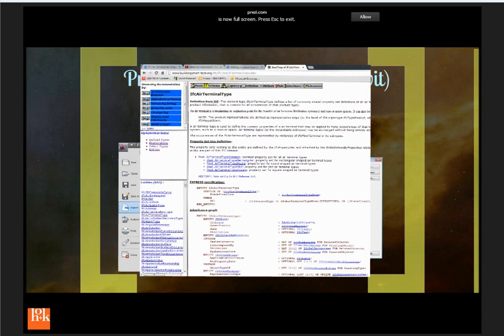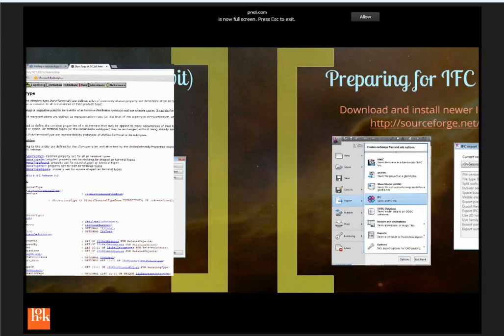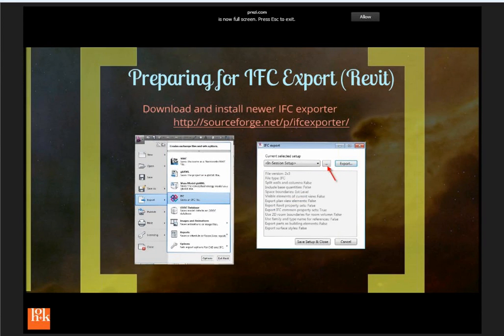So when you're using this thing, you want to understand what's what. And it can be confusing. For example, what would you think an electrical socket is? Would that be IfcElectricalSocket? Unfortunately, no, it's actually IfcFlowTerminal, because electrons flow through it, so it's a terminal for a flow. There's a type within that, so then it becomes a receptacle beyond that. So you have to look at the broad base first and then get into the lower ones. Now that's hard to do. All right, let's just go over this real quick.